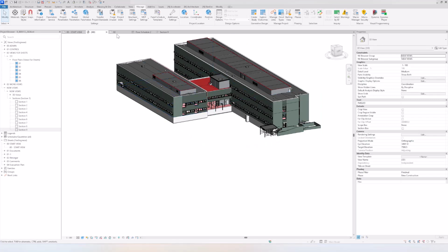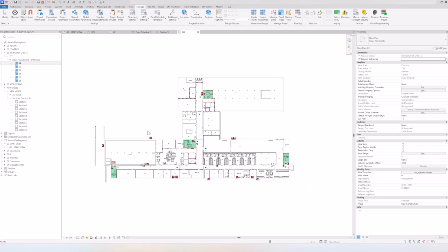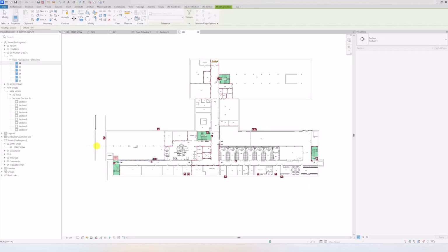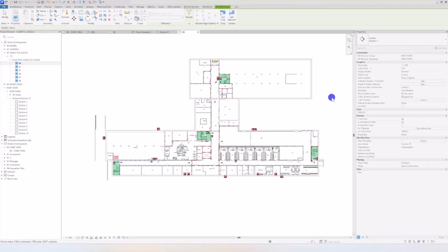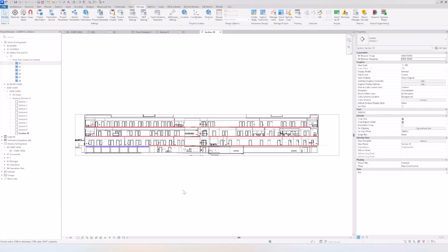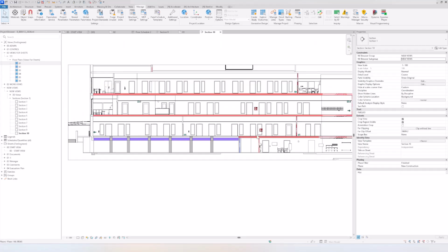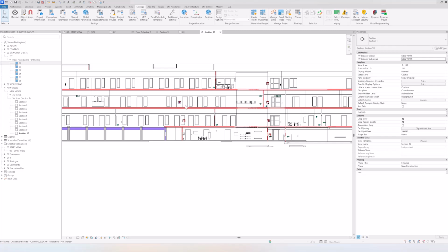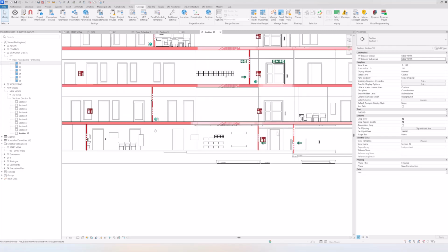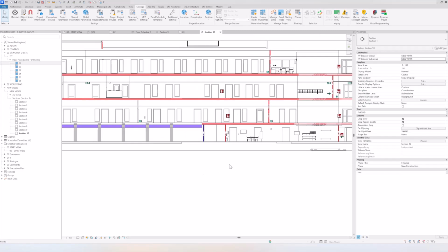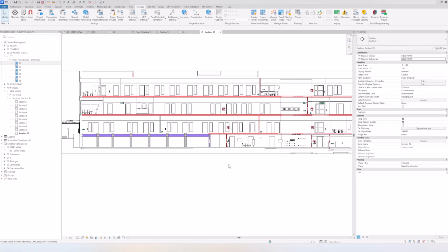We will get the exact same thickness, minus 2 millimeters, but the sections, everything, they're going to look a lot better. I'm going to go here. We can go through this one and just go through that one. We go to edit in view. We get everything here out of the box. We have a high requirement here. It goes up there. We can adjust this if you want, but we get these nice looking models out of the box, us doing nothing. And that's how we do the horizontal compartmentation using the Copy/Monitor feature.